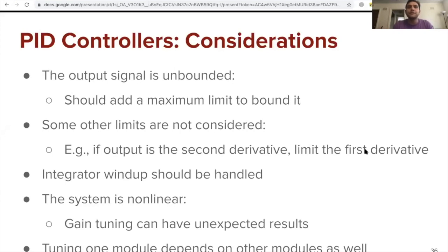If you are using the integral term, it's just an integration of your error over time. So if you have very large changes in command, for example, going from 50 degrees yaw to minus 80 degrees yaw, where the next command is to go to minus 80 degrees, during this change the accumulation of your error is very large.